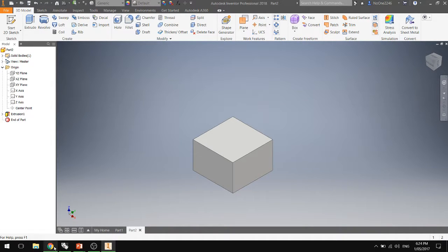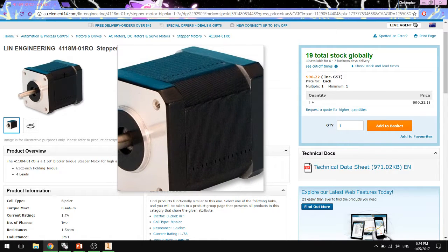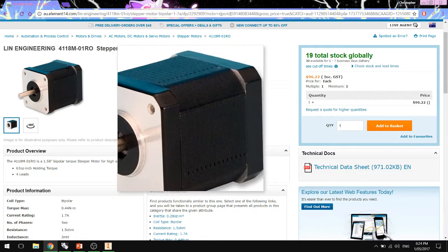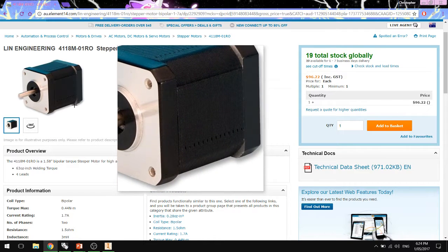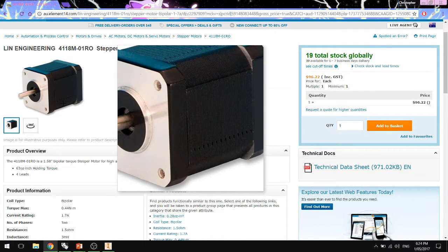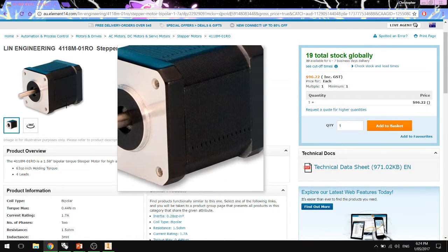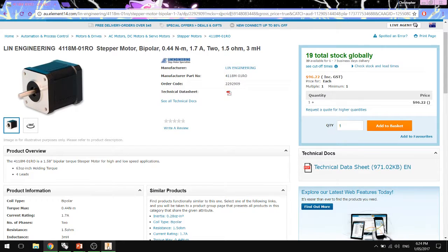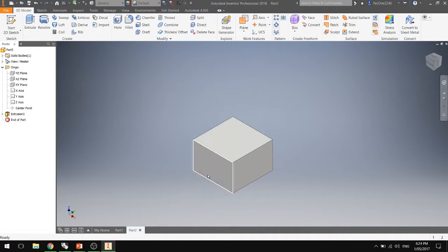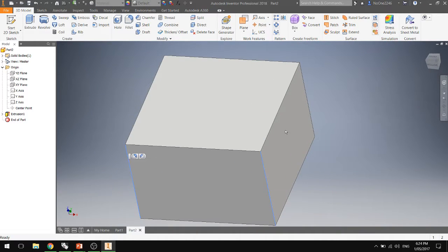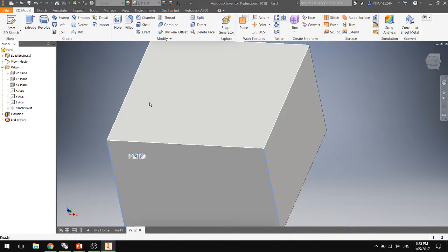You saw in the photo that these edges are kind of triangled off. If you see along here on the top, on each edge, it's called chamfering. So rather than trying to draw the sketch of that, there's a really easy way of doing it, which I'll show you. So what we'll do is select these edges. You may just want to select the tool and then select the edges. Yeah.